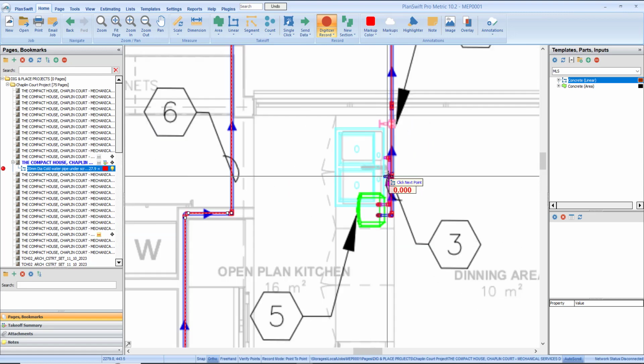sink is mounted at the height of, let's say, maybe 1.2 meter, or at the height of 0.9 meter, then you have to be able to know that yes, there's a particular pipe that is going to go up to that height, and then when you take your final calculations, you're going to be adding up that height to your measurement. So don't forget that you're going to have that height added to it depending on the level at which your sanitary appliance is being mounted.